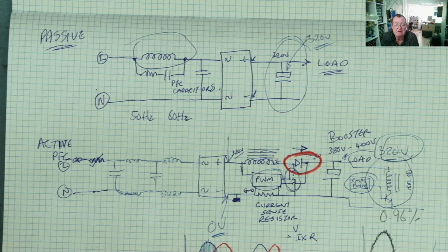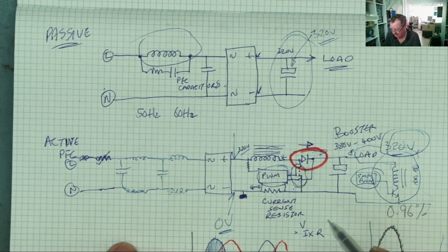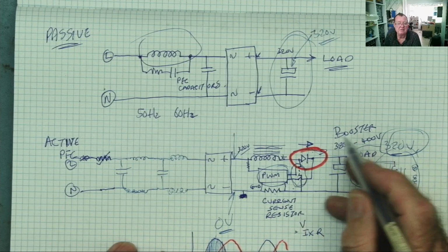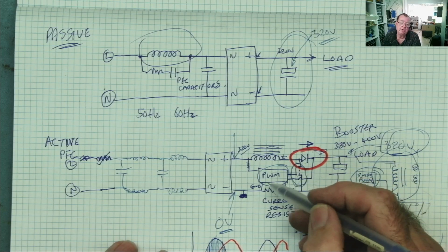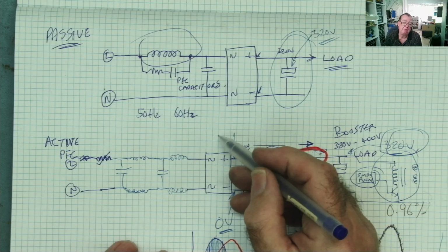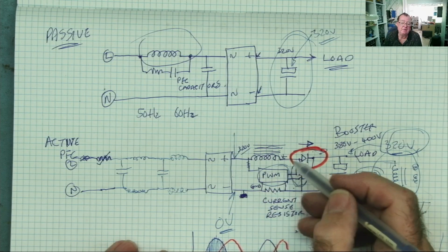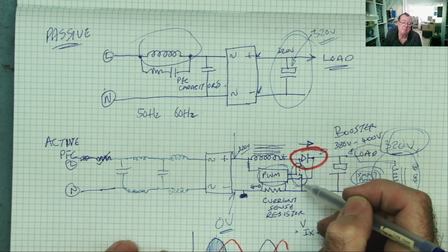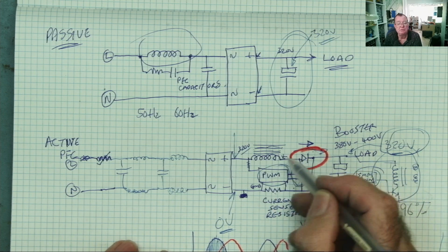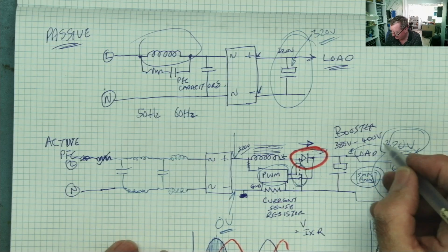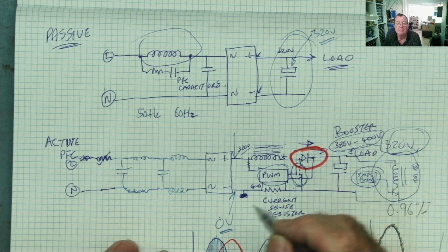It's not a difficult thing. It's not a difficult circuit. Usually if it goes wrong, it always goes wrong in the same way, or same ways pretty much. One thing I didn't mention, I'll just point this out now: the PFC is a booster, and it will boost the voltage up to this, and it's using pulse width modulation. If the voltage coming in is lower, then this will increase the on time of this MOSFET to draw more current into the inductor to increase the output and try to get the output up to that.